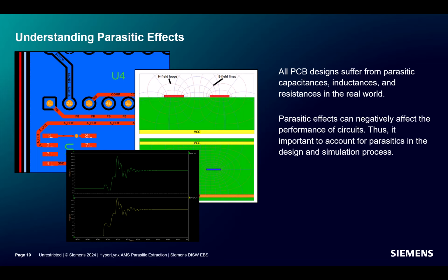For instance, trace parasitics can affect the characteristics of analog filters. In digital signals, parasitics can degrade rise and fall times, induce ringing, and cause bit errors. Noise coupled from digital signals can negatively affect the behavior of a sensitive analog signal. In power electronic boards, parasitics can cause unintended switching in nearby logic circuits. Correctly accounting for these effects in simulation requires an accurate model of board traces and their collective behavior.